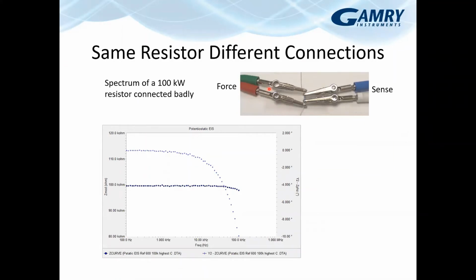So what's happened is these alligator clips are bare metal, and so are the banana jacks underneath. There is no shielding around them. They are going to have higher capacitance than the shielded cable before it. Additionally, even with shielding, it's not a perfect block of 100% of the capacitance, so there is additional capacitive pickup even in the cables before this.